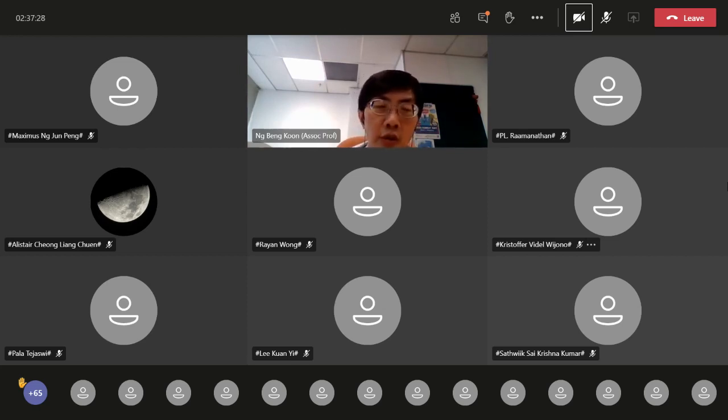Okay, so at ground state, where the fifth electron is not having any thermal energy, you will expect it to sit at the lowest energy possible, which is n equal to 1. So that's the lowest position that it sits, and in fact, this lower position corresponds to the donor level. For it to get to the conduction band, it has to go all the way up to n equal to infinity, right? Once it reaches infinity, then it's free to move, which corresponds to a position in the conduction band edge. So the binding energy will be the difference between the value of n equal to infinity and n equal to 1.